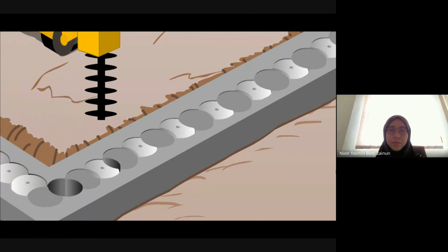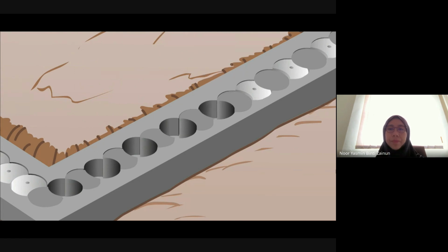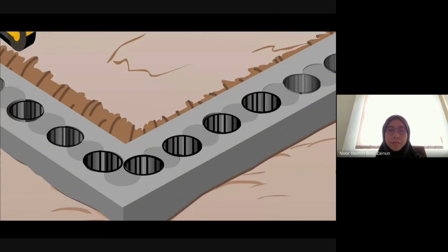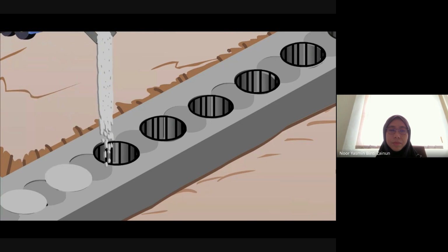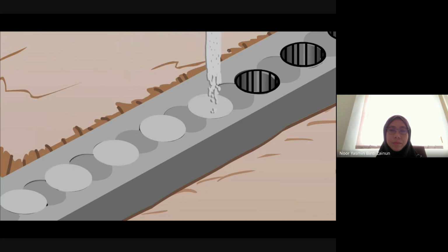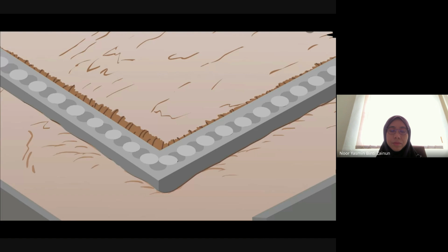The secondary or male piles are now drilled out. This action creates the important interlocking overlap between the piles. For reinforcement, a prefabricated steel cage is lowered into each secondary pile. A second hard concrete mix is then used to complete the wall. Some specifications require all piles to be made of the harder concrete. A secant wall completed to precise tolerances.